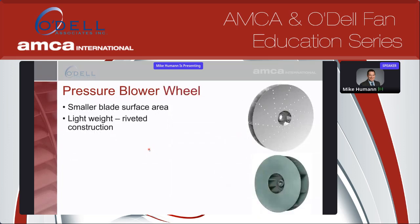Here's showing those wheels for the pressure blower. And you can see, again, we have a little bit different design, but it is still coming out radially from the hub. These do have a little bit of a cant to them. And this wheel actually rotates in the counterclockwise direction from our view. The top wheel is actually aluminum riveted construction. So that's specifically used for clean air applications.